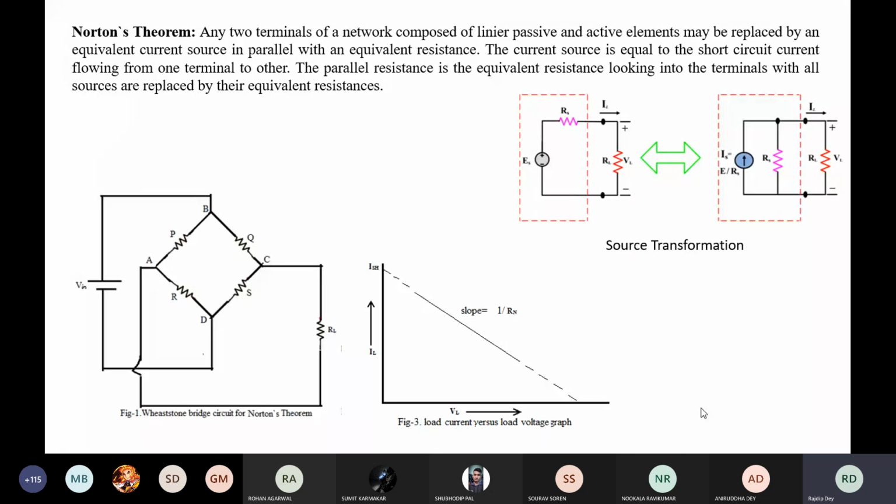So what we'll do, we'll take the minimum value of the load. Suppose we'll start from 5 ohm. We don't know, maybe we start from 3 ohm also, or maybe 10 ohm. When I will be doing the experiment, you will see that physically you don't know how much portion is what resistance. So we'll try to move very little by little, and we'll start from one end of the load. That means we'll take the minimum load resistance value.